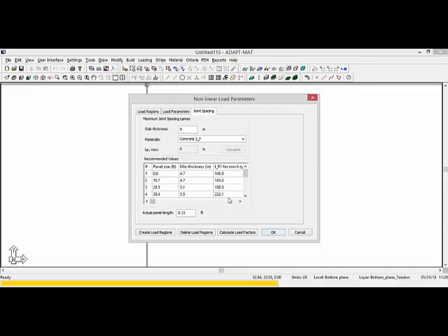Our FR1 value for the fiber that was selected was 377, and if we scroll down we can see that's roughly in between these two values here, which would put us at a spacing of about 60 feet, which is a slab thickness of 5.5. So we'll go ahead and select our slab thickness. We'll say the slab will be 5.5 inches thick. We'll just follow this recommendation. It might be slightly smaller than that, might be 5.